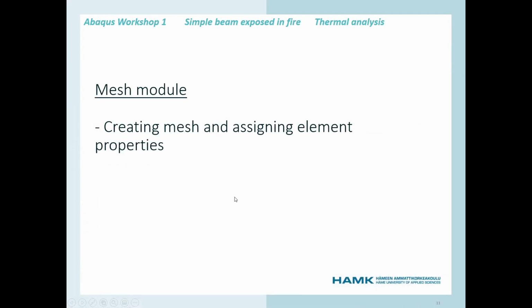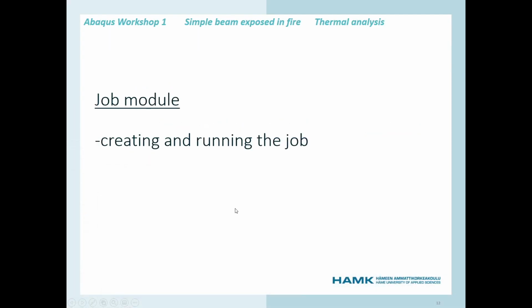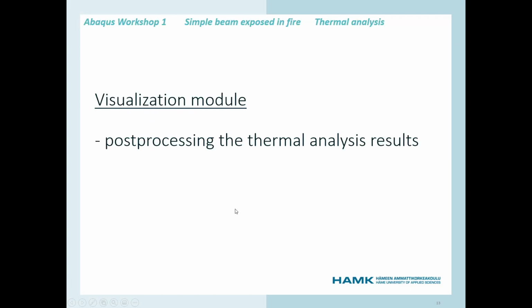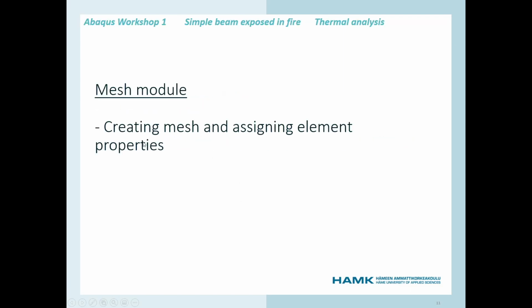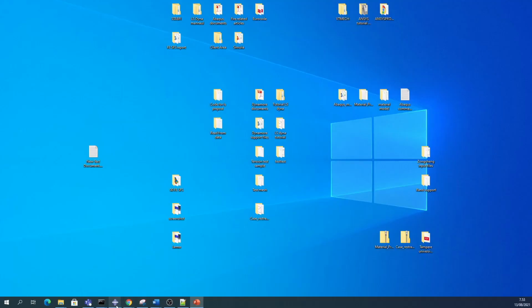is the mesh module. In the mesh module, we create a mesh, assign the number of mesh and the seed type, and also we define the element properties. In this one we define the heat transfer element.